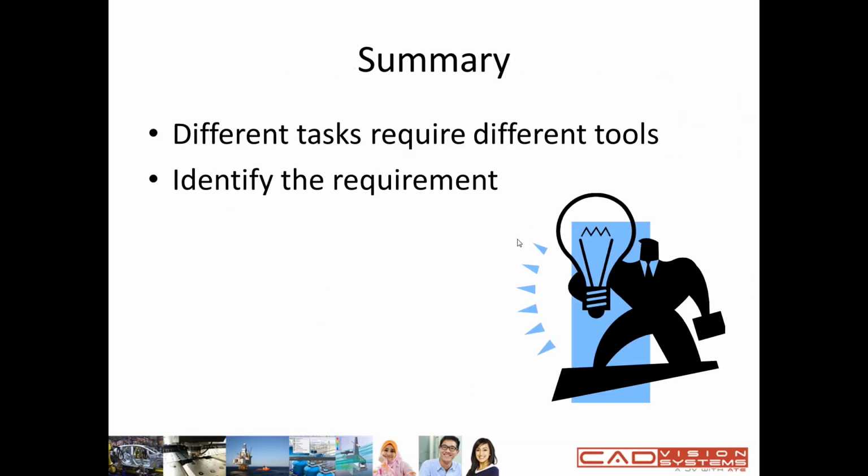Okay. For the summary, we talked about lightweight, large assembly mode, large design review, SpeedPak, and defeature. For extra information, there's another way to simplify your assembly, which is just using a configuration by suppressing components. It's like a manual tool to simplify your large assembly.